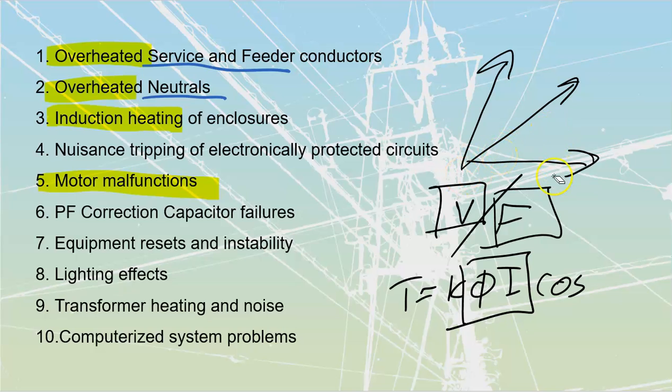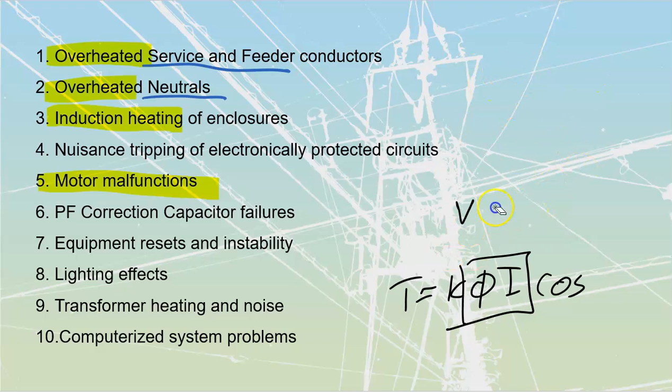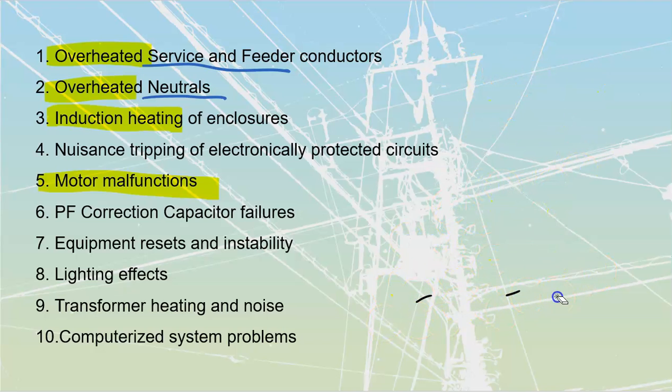The other issue is, once again, that we are going to have skin effect in our motor conductors, where we core out the center of those conductors due to that high frequency. As soon as we get skin effect in the motor conductors, we have more resistance, and therefore more heat. We're also going to have more heat based upon the frequency of the harmonics inside of our system. So the motor casings, the motor cores, stators, and rotors can overheat. So lots and lots of problems with motor malfunctions.